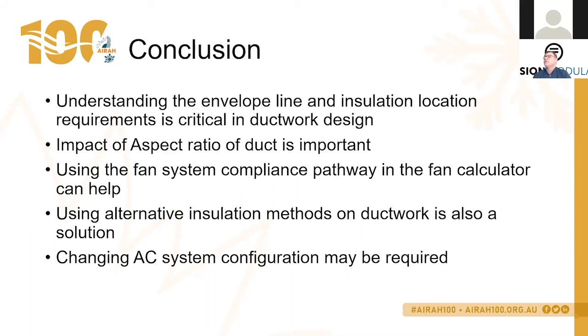What if we need to have more than 6 metres of flex duct? Any solutions? Do a performance-based solution. You will need to demonstrate the energy efficiency difference or lack thereof, or energy efficiency improvement that you can achieve by using more flex if you wish.